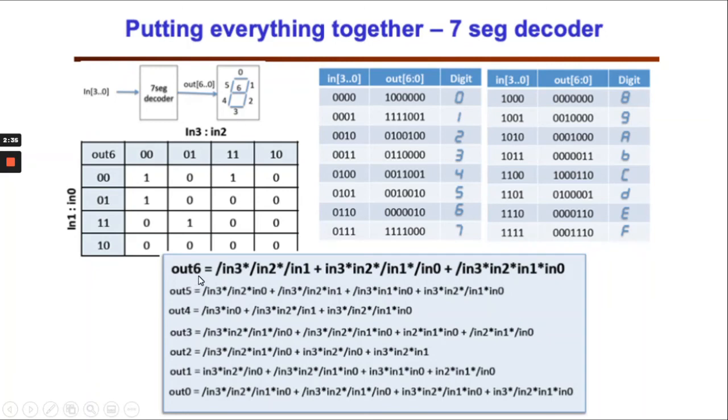So we can imagine that it looks complex, right, if you want to design the BCD to 7-segment converter by using the gates itself, right? And this is the truth table, how we can construct the 7-segment. I've explained this in lab, right? So for example 0 here, all bits need to be 0 and just one bit is 1, because the 7-segment LED is active low. So all of the signals need to be 0 to light up the LED except bit 6, right? So bit 6 will be high, then it's not going to light up, right? So the rest of the LEDs are going to light up, forming a 0 number.